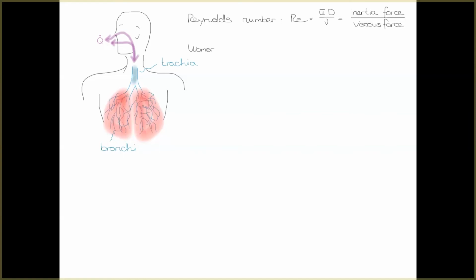And this is basically the scaling of the relationship. Then there is another number which is important, the Womersley number. The Womersley number also scales with a ratio of unsteady inertia forces and viscous forces. In other words, if the Womersley number is very small, then we can always work with quasi-steady flow solutions. Then the flow velocity is only changing because the boundary conditions are time dependent.